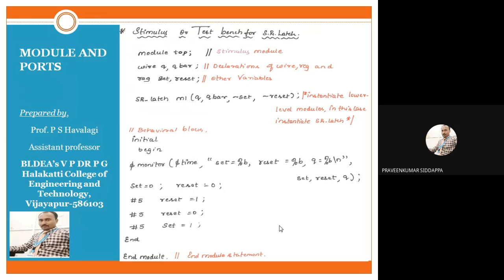Where should we write it? Before initialization of your inputs, we should monitor the inputs. If you are monitoring afterwards, then that would not be helpful. So because of that reason, before applying the monitor statement, next we should provide the inputs.